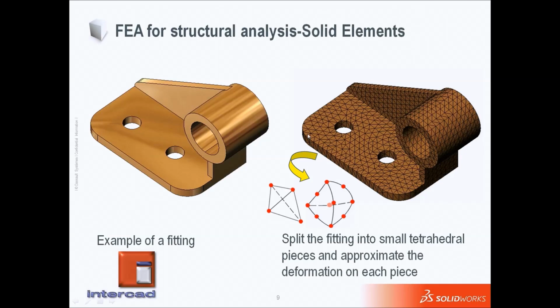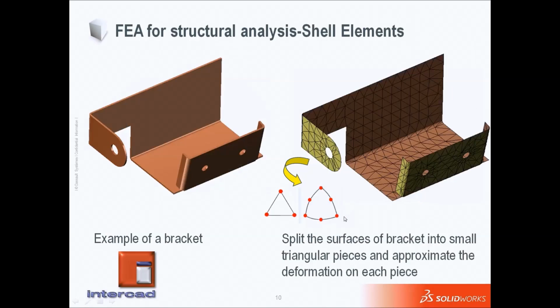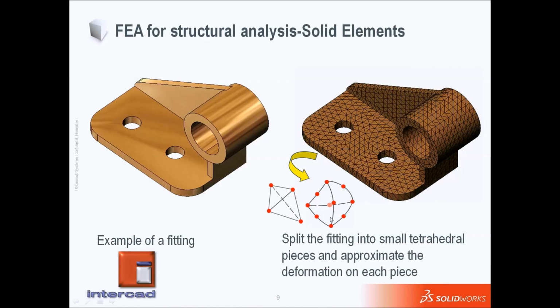Each element is put on the whole structure. Or if we like higher quality meshing, we put in a higher quality element, with 4 corner nodes and 6 middle nodes on the edges. So more points to calculate means a more accurate result but very time consuming. Fewer points to calculate means a rougher estimation, but fast calculation.